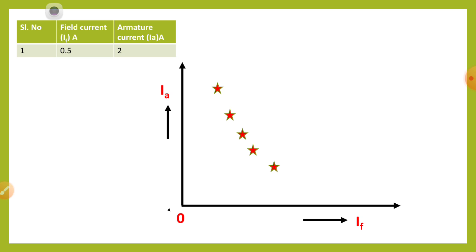Now further increase the field current, then what will happen? Here the current is increasing. Further increase the field current, and the armature current goes on rising. At one stage of field current, suppose for example you take a rubber band. If the rubber band is stretched to a limit value, it stretches perfectly. If further force is applied, automatically it will break.